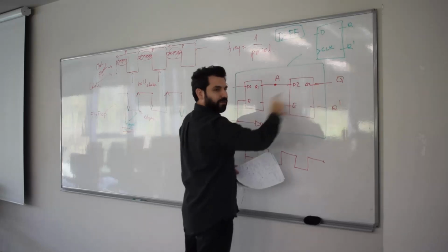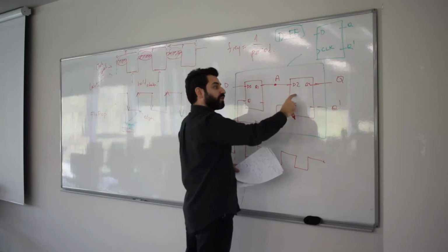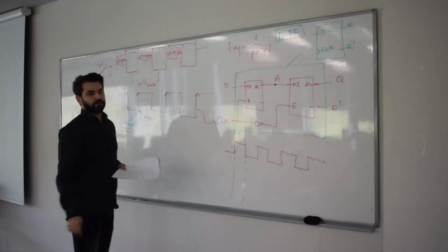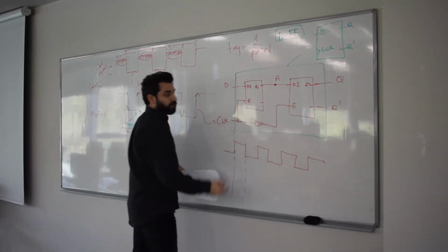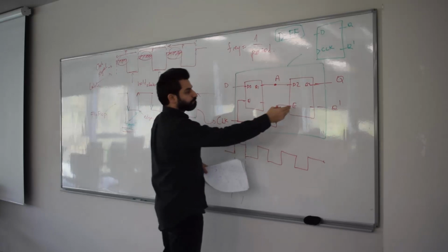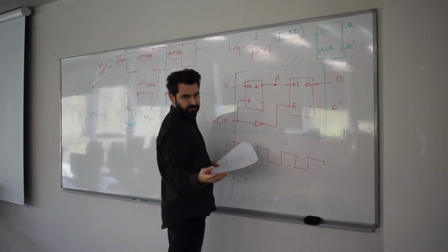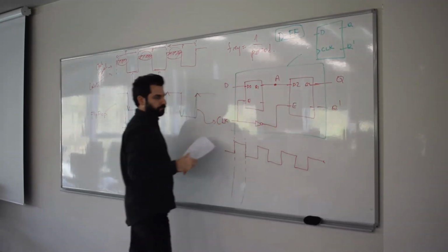So what is it pushing out at that particular state of time? It's pushing out what this latch was storing in the previous round. Okay? In other words, when enable was 1, but we don't have that yet, right? So it's just pushing out some random number.